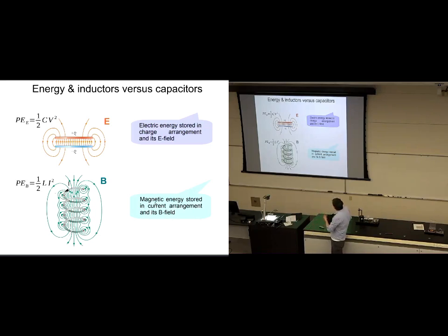Okay, final equation. We met, when discussing electricity, the energy stored in a capacitor. You could write it as 1/2 times the capacitance times the square of the voltage. That's one way of writing it. It said things like if you double the voltage between the plates of a capacitor, you'll quadruple the energy that's stored. There's a similar equation for the energy that's stored in an inductor.